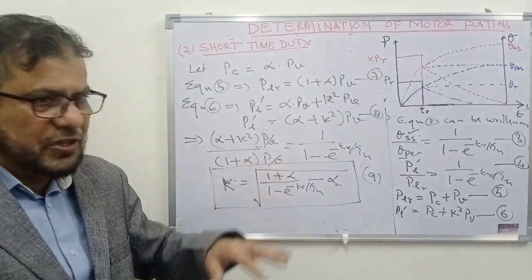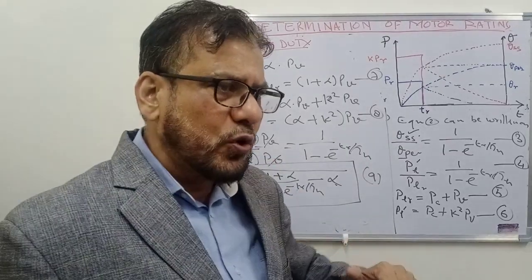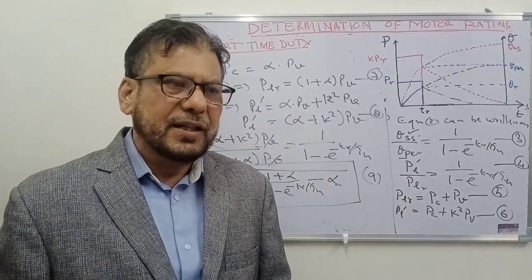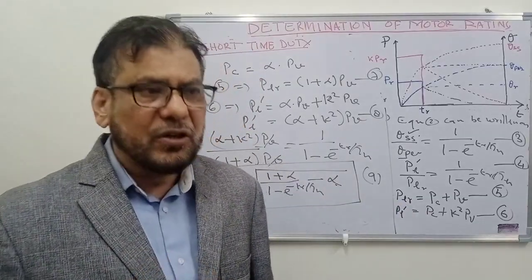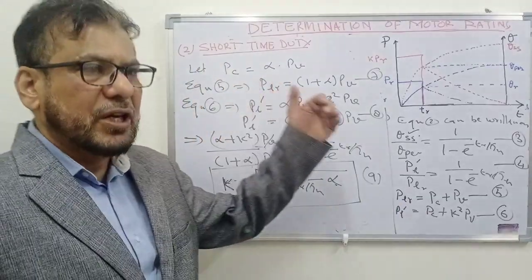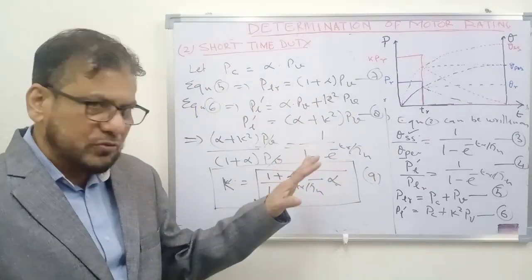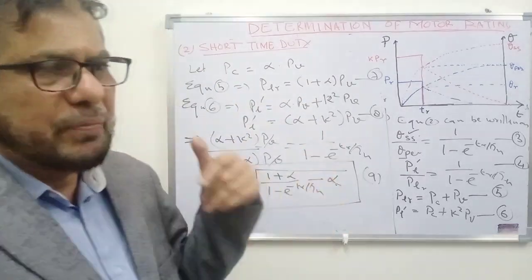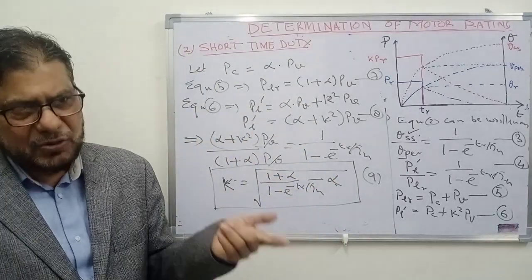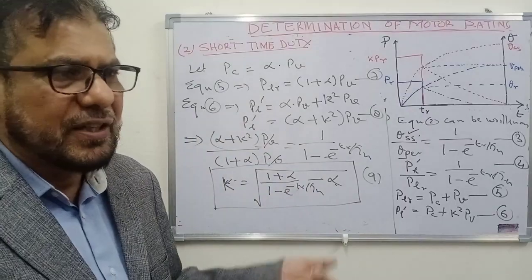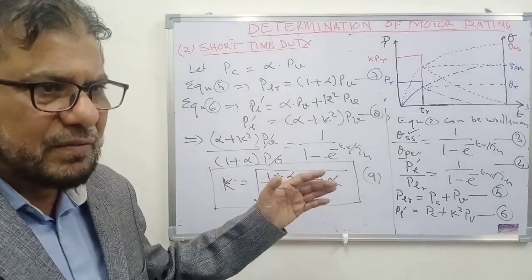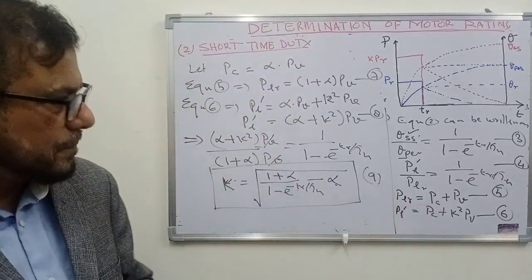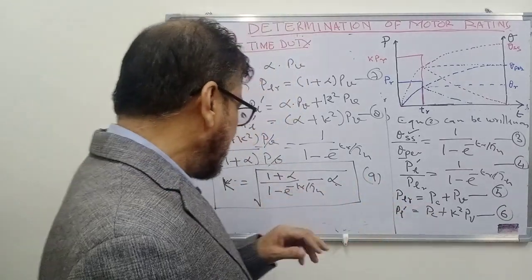Similarly, in the case of an induction motor, if you overload the motor, the torque will also increase and the motor has a particular breakdown torque. You cannot go beyond the breakdown torque of the motor. So that limit has to be seen before you overload the motor. If the breakdown torque is twice the full load torque, you can go up to twice the rated load on the motor. Otherwise the motor will cross the breakdown torque and come to a standstill. So you have to take care of this.